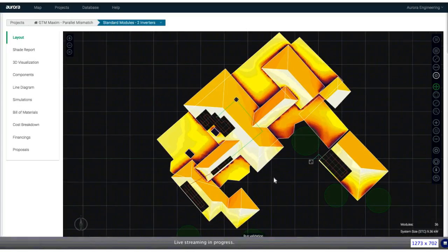And just looking quickly through it, toggling our irradiance map, you can see we basically just tried to put panels on the bright spots. Those are receiving the most amount of light. We do have some panels around that chimney towards the back of the house. That's going to cause some shade and potentially lead to electrical losses. We have another string spanning multiple roof planes facing southeast and facing southwest. They receive a little bit different amount of light, and so we will have some serious mismatch effects there.